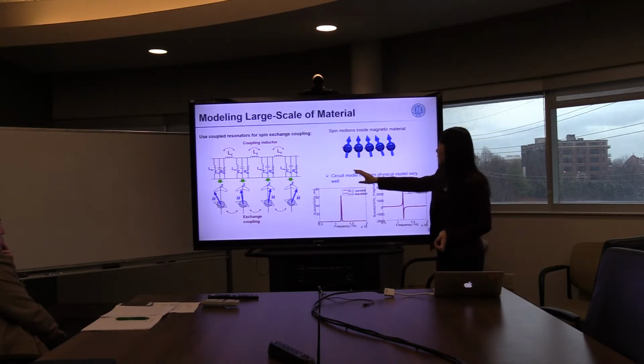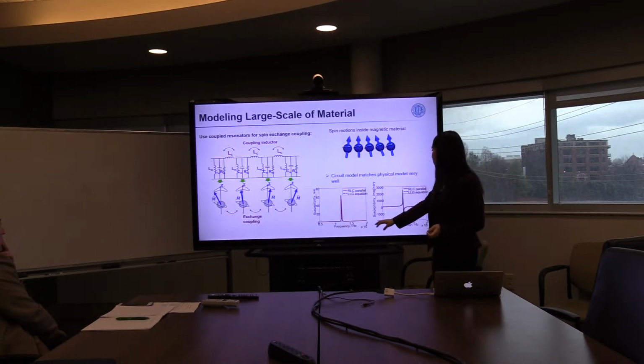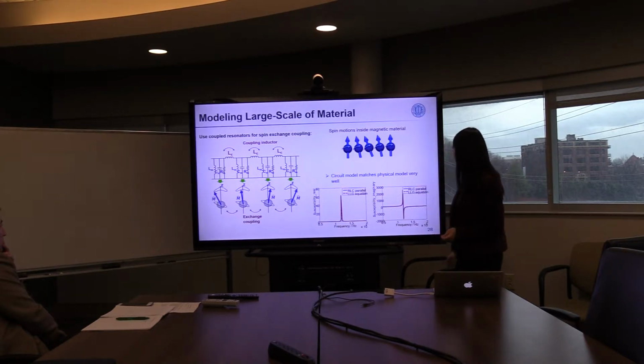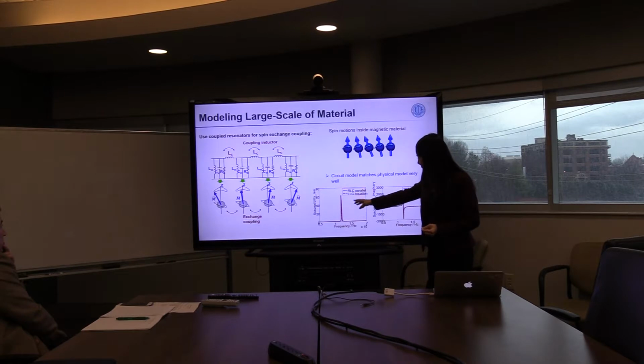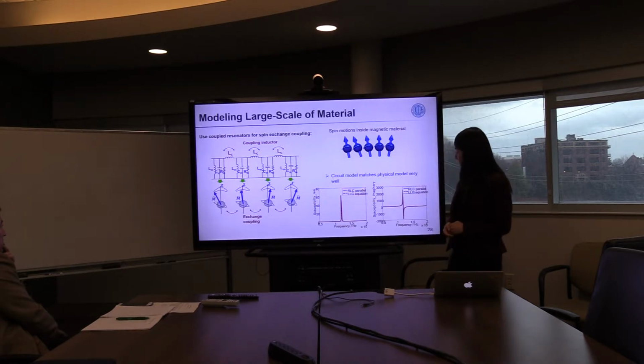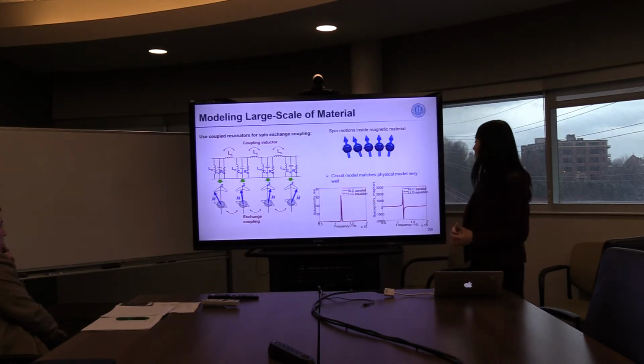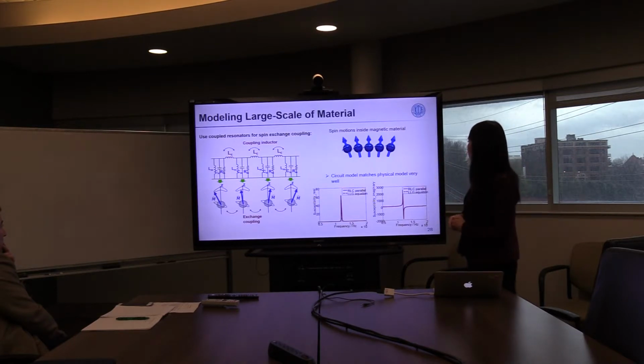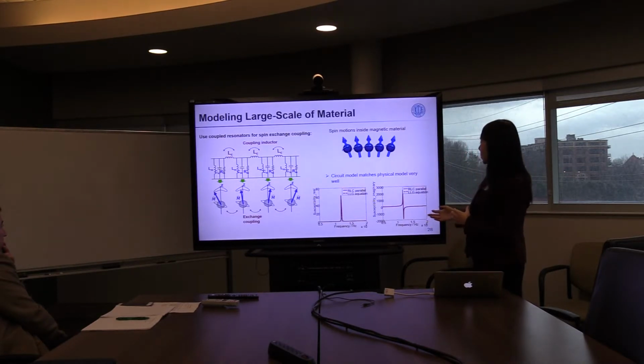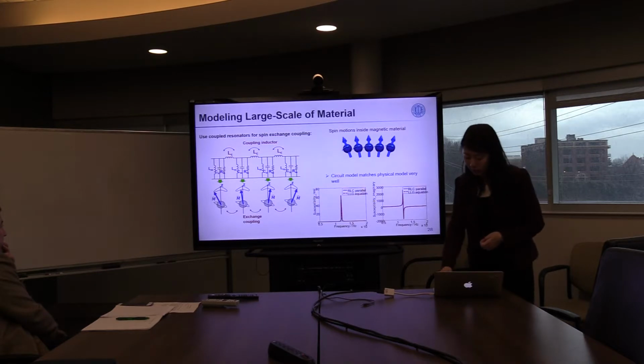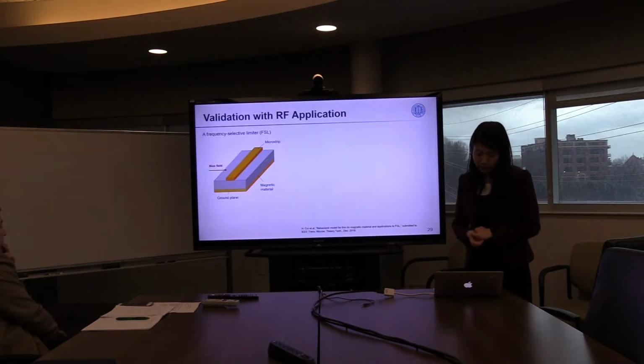And this circuit model gives us a very good prediction of the frequency dependency in terms of the resonance of permeability, both from the real part and the imaginary part, which validates our assumption that we can use this macro domain circuit model for some large-scale performance simulation.